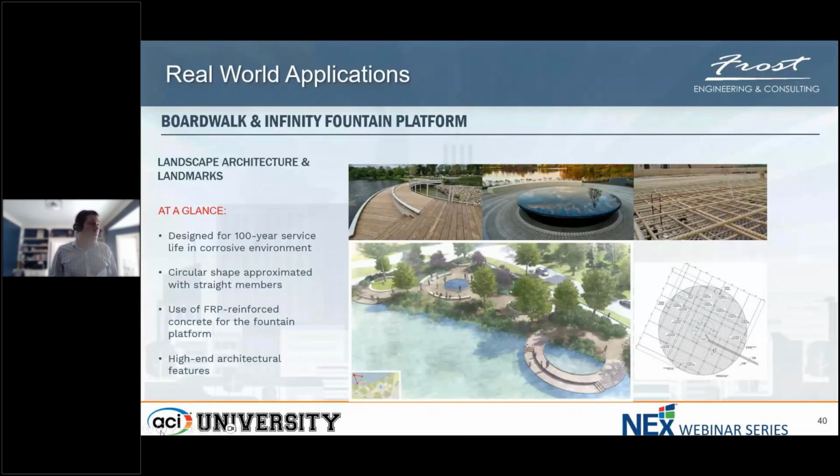So we were very highly worried about corrosion on steel framing if we're targeting 100-year service life. So we made the argument that we wanted to use pultruded FRP framing. Obviously, it's a bit difficult to camber those horizontally or curve them horizontally, so we did end up laying this out sort of multilinearly, but it worked out really well. The framing is underneath some very nice Kebony, as I understand it, artificial ebony boardwalk. It turned out very nicely, and it's sitting on top of some helical piles that were drilled down into the lake muck from the shore side.